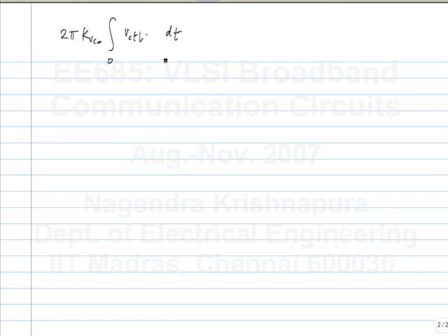Now let's say 0 is the time at which you start this. Okay, at time 0 the phase is the correct one, and you want to see how long it takes for it to drift, right? Sorry, you want to find this T max, at which point it becomes equal to, in this particular case, so this is one data period. Okay. So we say that this edge can be here, but if it goes and crosses this period, it's no longer useful. Of course, in reality, it should be some fraction of this. Okay, you can't let it drift all the way to the edge of the data period. But let's say it is this, so you have to solve this equation.